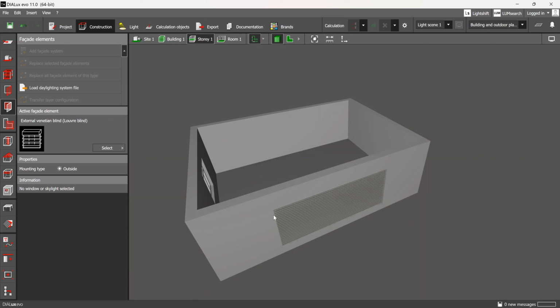The daylight you receive on this window, parts of it will pass and go through into this room. That one is transmission, which is transmitted through the window, and part of it is reflected. Normally, double clear glass has a transmission value of 0.88. That's for double clear. If it's low E or something else, it will be different, right? Some people use 0.8 as well, depending on how they measure it. Okay, so we have the same value for the wall.